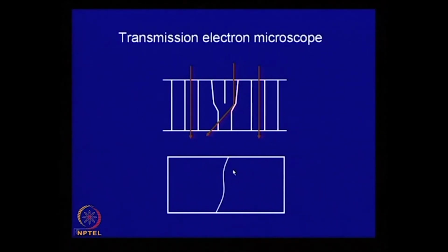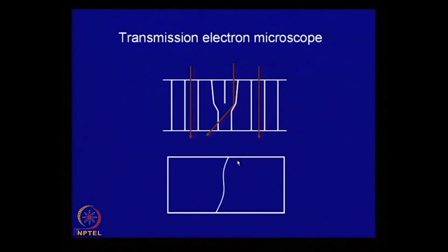The transmission electron microscope has several other advantages also. The electron beam has a wave character, so you can also record a diffraction pattern. If you block the transmitted beam and remove the projection lens, then the diffracted beams fall on the image plane, and these diffraction beams give a pictorial description of the orientation of the foil plane.